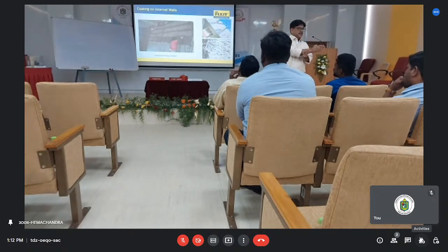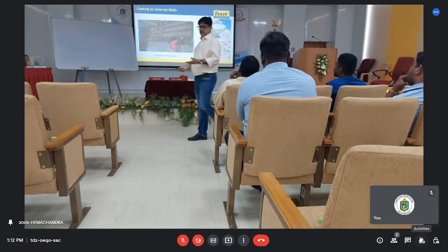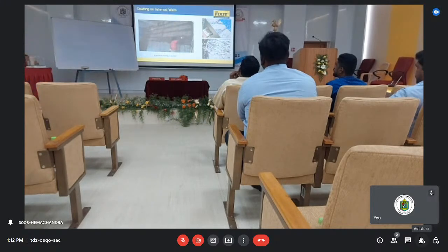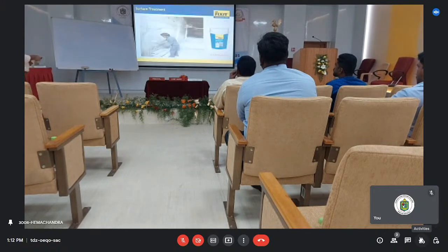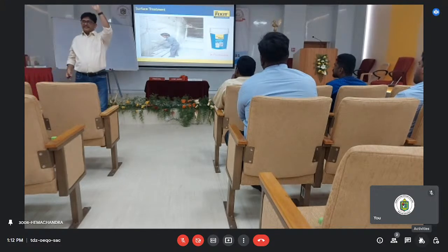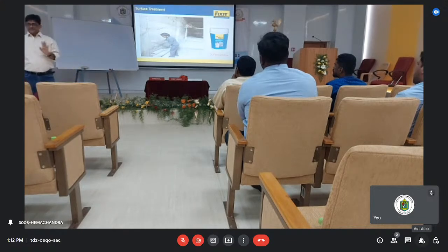But I cannot reach the positive side right now, so the surface I cannot do. That is done with the crystalline coating application. That is what we have shown here: the crystalline on the entire surface, the construction joint by the putty, and then the entire surface by the crystalline coating. Clear? Okay.